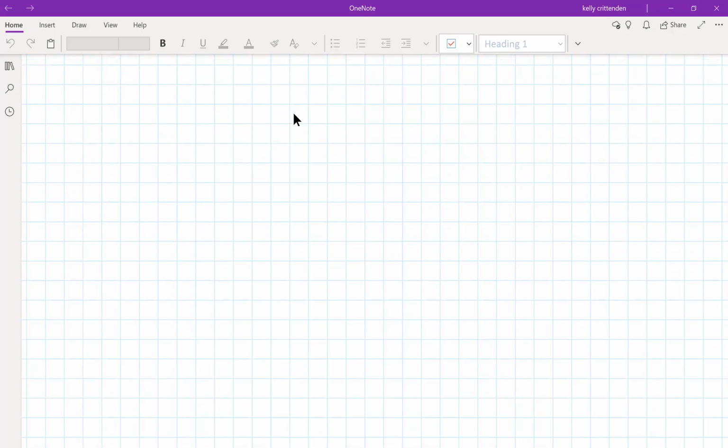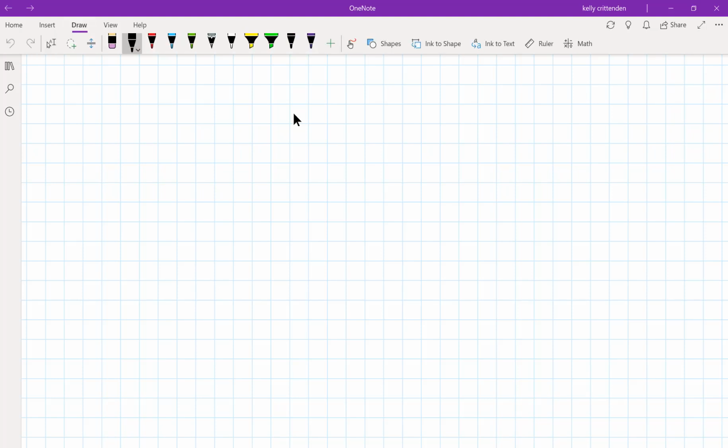So we have built basically a voltage divider. So remember, we have 5 volts. This 5 volts here is not the reference voltage. This is the 5 volts powering our little thermistor setup. And it goes into a thermistor. So this thing changes its value with temperature. And it's nominally 10,000 ohms. And then we've got a node here. And we've got a static resistor that does not change. And it is just 10,000 ohms. And we go to ground.